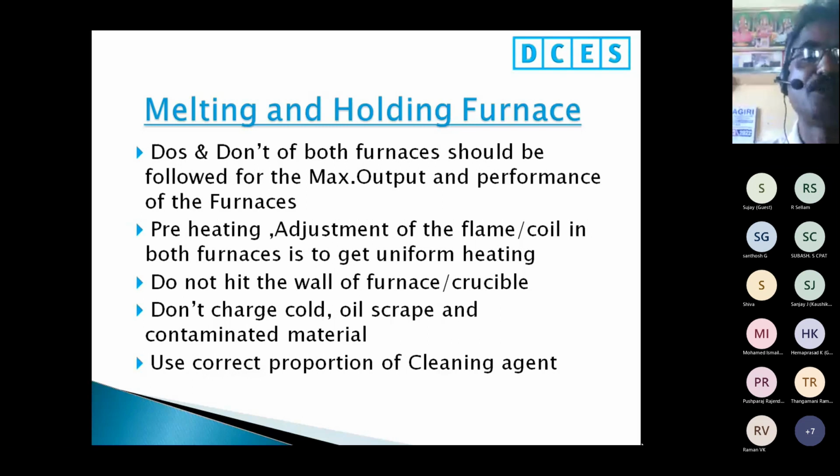And use the correct proportion of cleaning agent. It should not be approximate. When you have a 250 kg holding furnace, 250 grams should be used, or as per the supplier recommendation, and you also have to do validation properly. These are all the basic things. That's why I again insist on the basics.